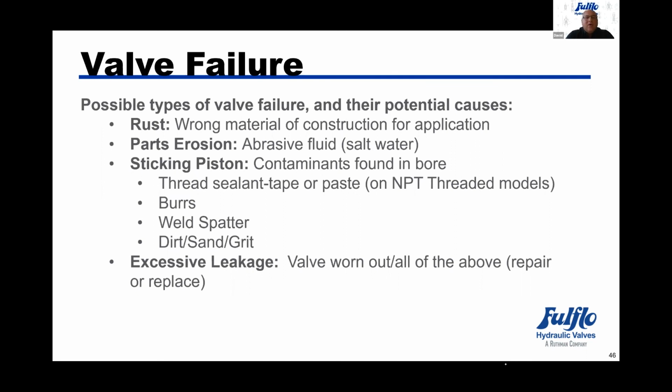The main reason why a valve would fail is the piston inside is sticking. There are contaminants in the bore that could be anything from thread sealant or plastic pipe dope for the threads. We get burrs, weld splatter, just dirt, sand, and grit. That would all prevent the piston from sliding inside the valve.